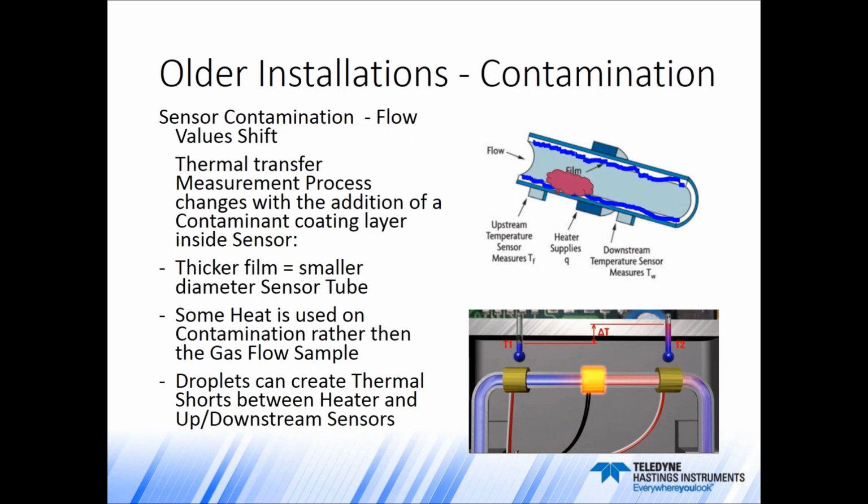So the MFC will blast the valve open and then close, and then open again and close. The whole process has to do with the fact that the thermal transfer process that happens in the sensor, instead of being a smooth, clear operation, reaches a high point and a low point, and this will trigger oscillations of the flow controller or total catastrophic malfunctioning of the flow sensor and the flow controller itself.